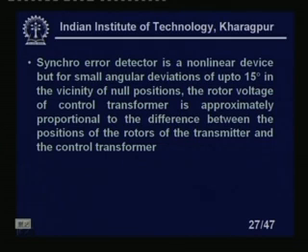Synchro error detector is a nonlinear device, but for small angular deviations up to 15 degrees in the vicinity of the null position, the rotor voltage of the control transformer is approximately proportional to the difference between the positions of the rotors of the transmitter and the control transformer.